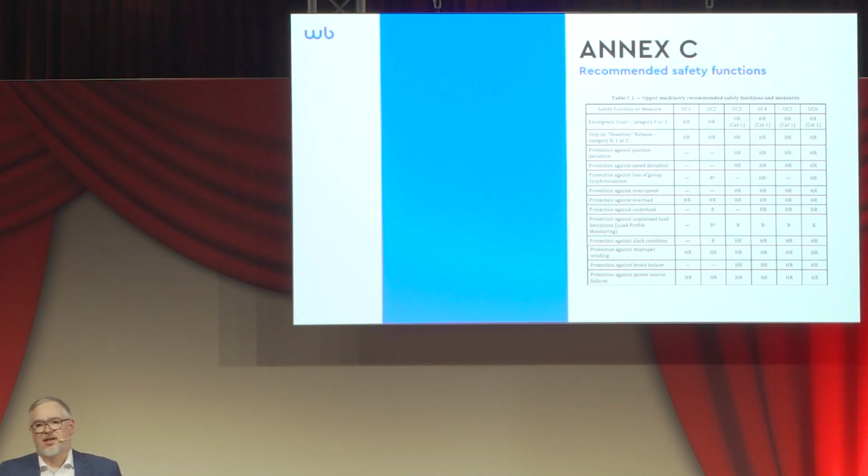These use cases define what is the intended use or typical hazard that is implied by this machine. So UC1, 3, and 5 are always statically deterministic loads, individual axes that are being moved, and UC2, 4, and 6 are about synchronized motion, where several machines are used for synchronized moving equipment around. UC1 is lifting machines where hardly anyone is in the hazard zone, the typical rigging chain hoist that you would use for setting up a temporary stage, for example.